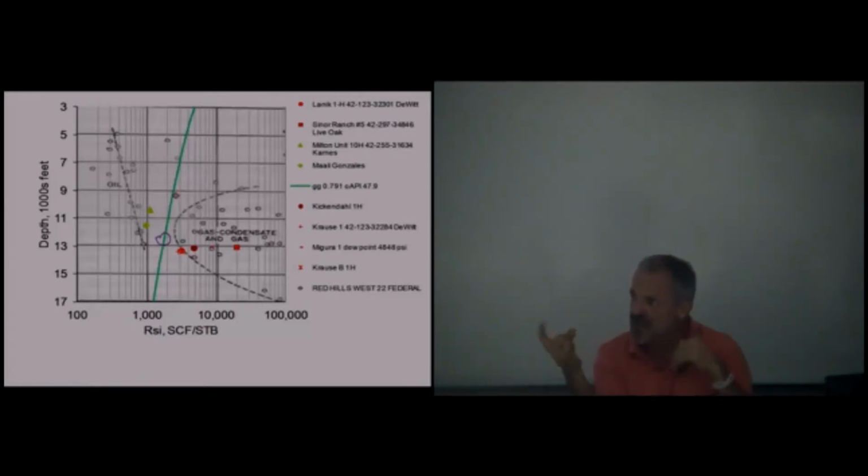And that's because for liquids, there are very small gradients in viscosity with pressure. The viscosity doesn't change very much with pressure. With oil or liquid, the compressibility also doesn't change very much. So when we derive the diffusivity equation or the characteristic fluid flow equation for liquids, we assume constant compressibility and viscosity.